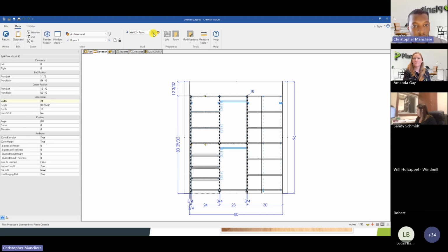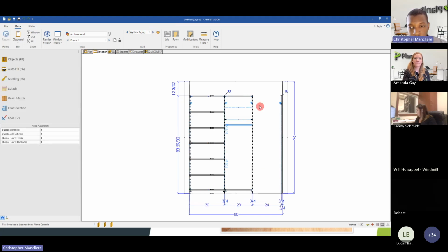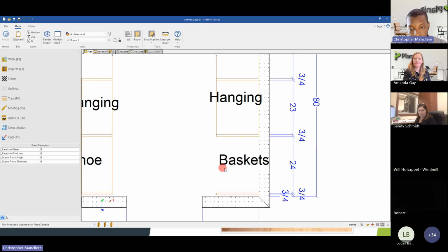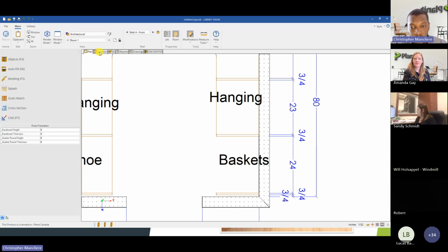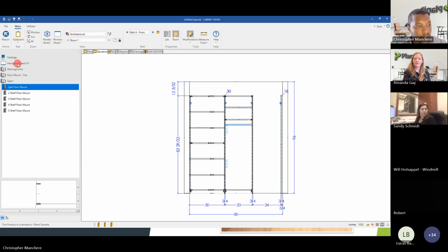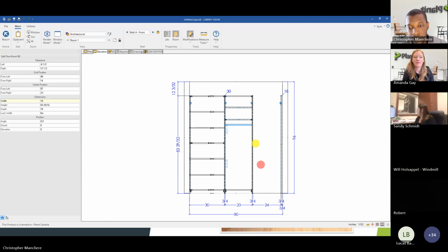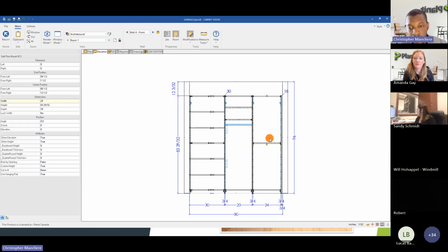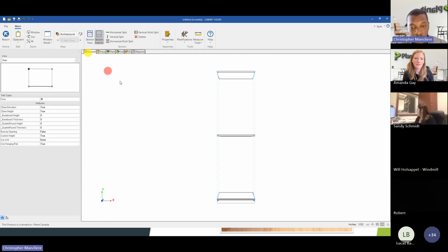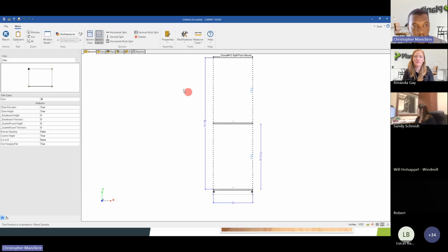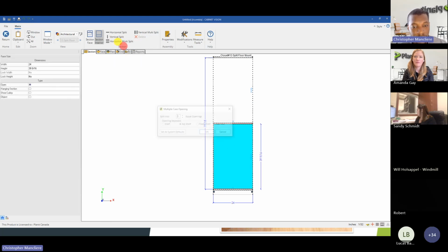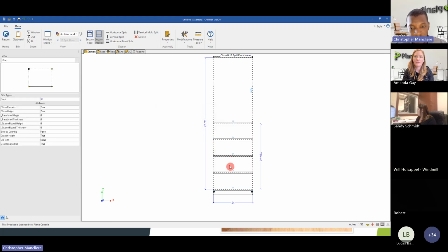The other side, I will want to include a wire basket on my third wall. So right now we want to fill this opening here. So I will go in my object. I can actually use the same split floor mount unit. And what I want is the bottom section will be a couple of wire baskets, and on top will be adjustable shelf. So let's do first those wire baskets. So I'll split this in 4, for example, because I want 3 wire baskets.